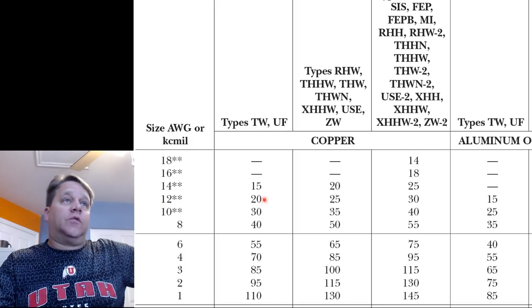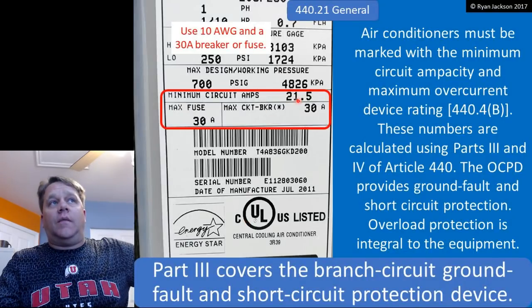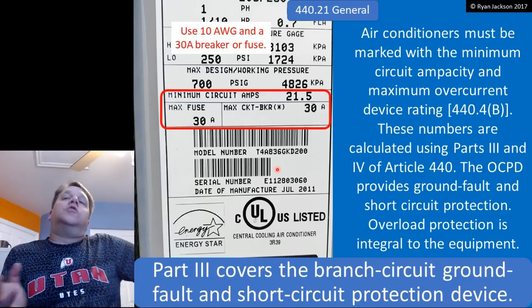12 gauge is only good for 20 amps. So I need 10 gauge, right? I need 10 gauge wire because that will carry 21 amps. And then all I have to do is go off of the nameplate, 30 amp fuse, done. That's it. All right? Now, are you comfortable with that?